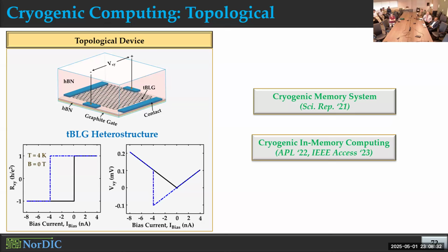So I'm not sure about the circuitry, but we can obviously do some device level simulation to observe the behavior in the interface. That's what people have done already. For the ferroelectric SQUID, you have a ferroelectric, which is non-superconducting. Then on top of it, you have the superconducting device. In the interface, the charge density changes based on the polarization state of the ferroelectric, and that dictates the superconducting behavior of the superconducting device. People have tried to simulate what happens in the interface to observe what happens eventually in the superconducting device.